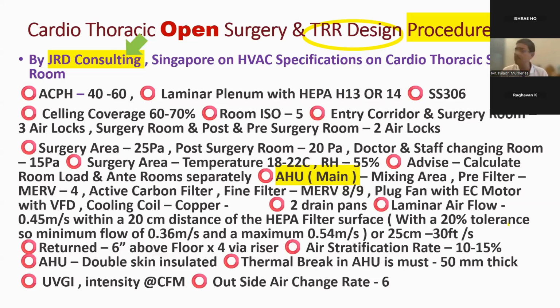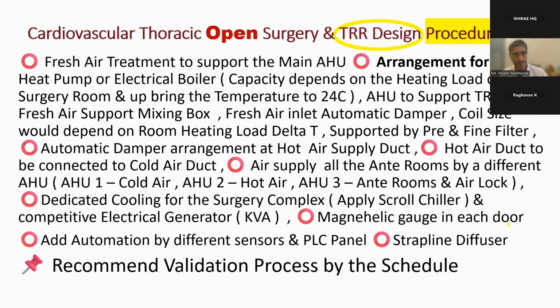UVGI is very, very essential. I will show you all. The UVGI should be there. And the outside air change rate, I told you that apart from ACPH, outside air changes are mentioned separately, it is 6. So that's fresh air treatment to support the main AHU. I'll show you in the diagram, there's a main AHU which will be supporting the